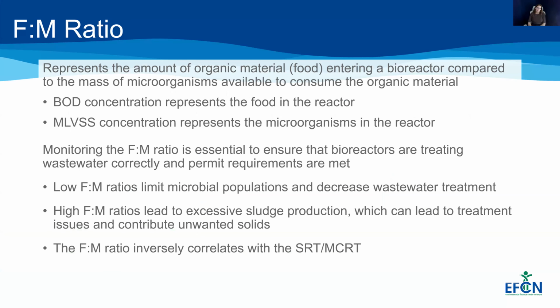Now, the first calculation that we mentioned is our F to M ratio. This is our food to microbe ratio, and this represents the amount of organic material or food entering a bioreactor compared to the mass of microorganisms available to consume the organic material. So the BOD concentration, or the amount of BOD in the reactor, represents that food factor and the organic material that's available, whereas the MLVSS concentration represents the microorganisms in the reactor that are available to consume that organic matter.